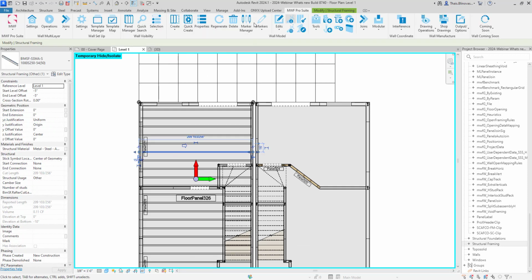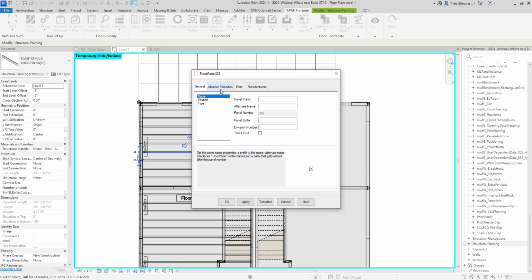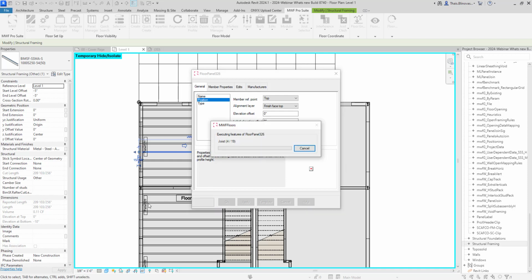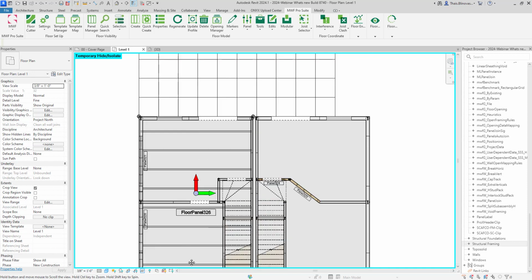So if I go here to my properties again, and I go back there to my spacing benchmark, I can see now that I do see the BMG, which is the grid one. So you can actually use this one now for floors and not just the default benchmark.